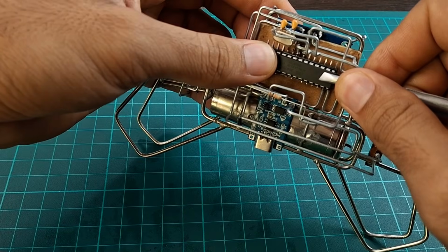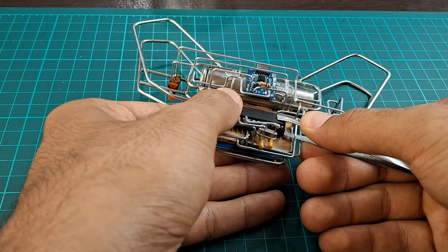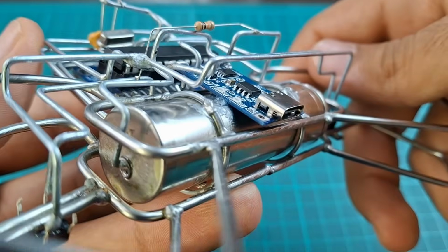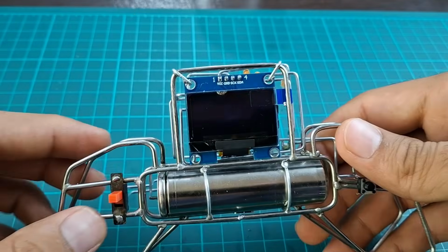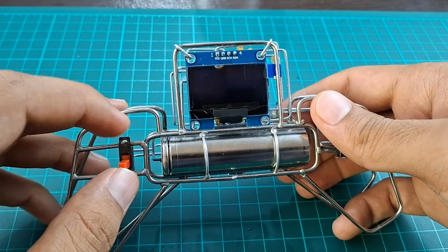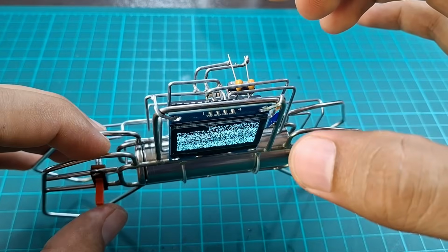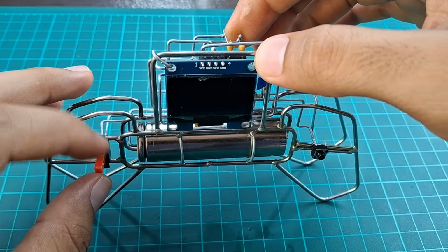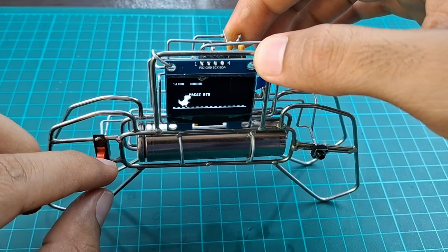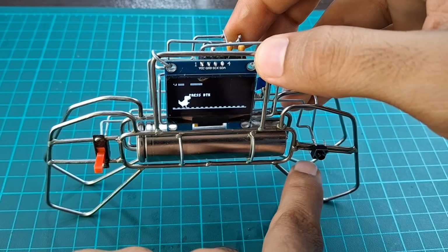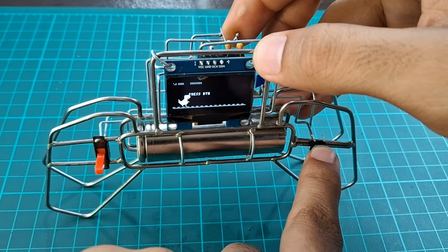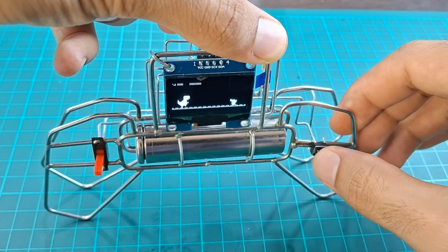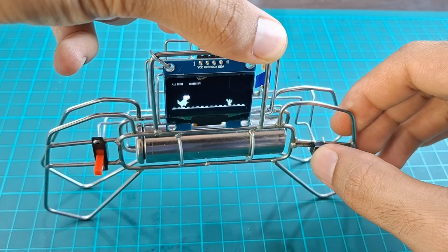Let's put the chip into the socket and see if everything works. We don't need that anymore. Alright, this is what the back looks like, and now if we turn it on, nothing. Then I noticed this. I thought maybe the crystal pins weren't properly connected to the ground. So I touched them, and suddenly we can see the Dino. But it doesn't jump. I tried it one more time and it's working.